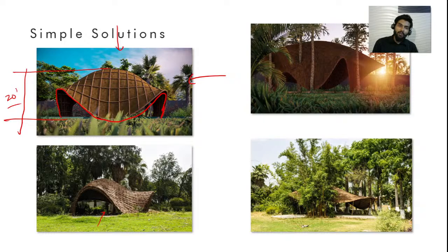The people that we had to work with were people who made bamboo structures but not complex as these. So we had to give them drawings from which they could make sense. So what we did is we exported drawings from Grasshopper itself that had all these dimensions and where exactly the bamboo would be bent. We sent the bamboos to the fabricators. It was bent through machines and pulleys, and then it was brought to the site and assembled by three bamboo workers, and you can see it realizing in real life.